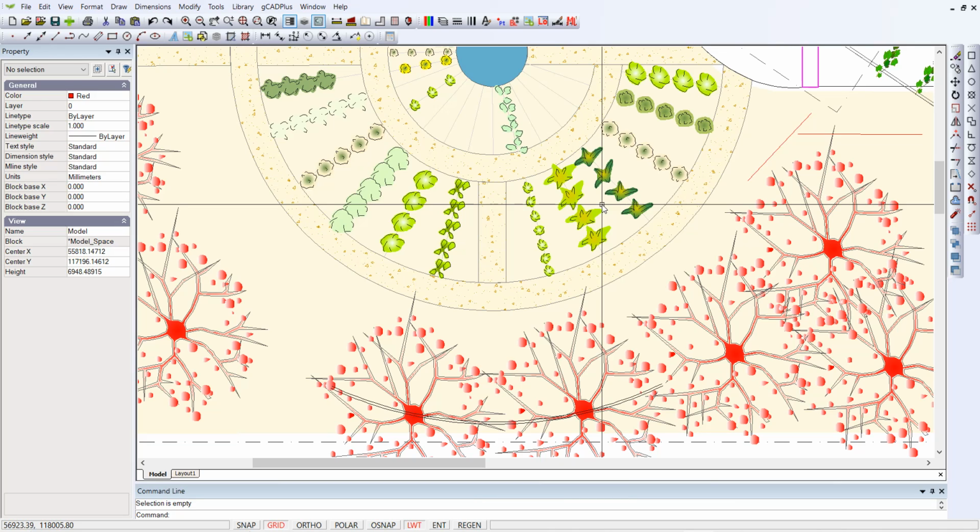Two things: enable you to set a fill for background and adjust your colour very nicely, and also if you have a lot of symbols to put in, as we do in this instance, we can use the copy along a line to very easily put multiple symbols along a particular path. The path can be a polyline, rectangle, all sorts of entities can be used.